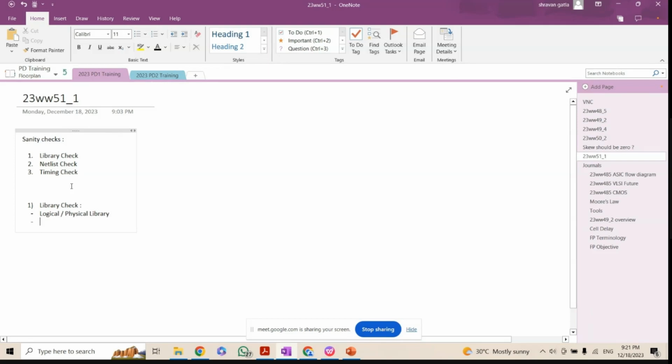In the ICC2 shell, timing may be met, but this is just the tool where you implement your PNR, place and route execution. This is not the sign off. ICC2 is not the sign off, guys. Sign off tools are different, where the checks are done and all the results are accurate. If this sign off tool says good, then only will you exit the partition. Otherwise, you will still be doing it.